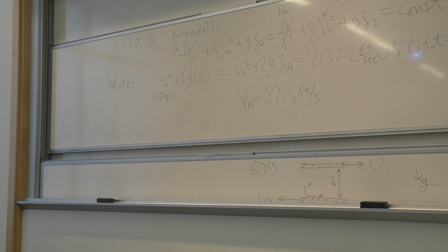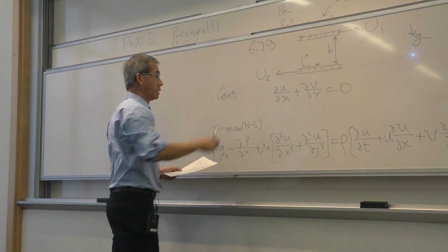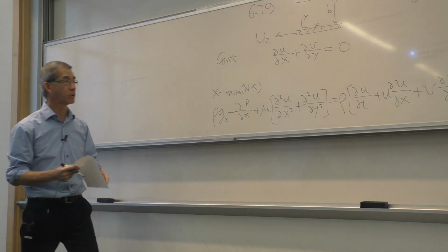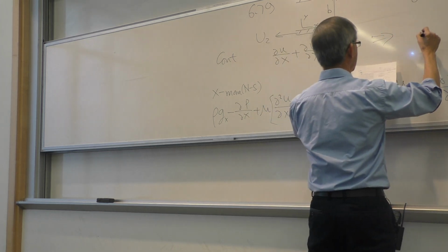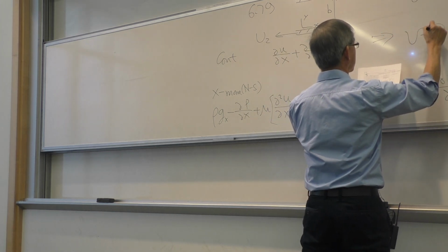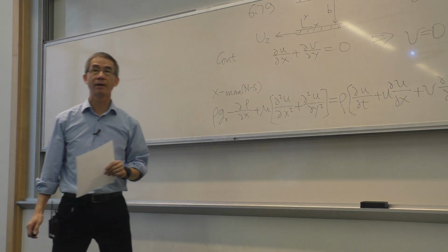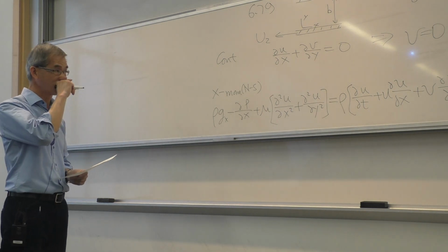All right? Other questions on this? Okay, so let me shift here to the homework problem due today. Very quickly, there's not much to it. I didn't talk about the continuity equation. This kind of fully developed flow is very simple because the flow is fully developed. The conclusion from continuity, I hope all of you see it when you apply the boundary condition, is that the V velocity is also zero everywhere, not just on the solid surfaces.